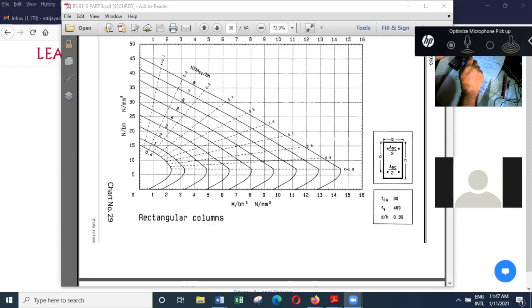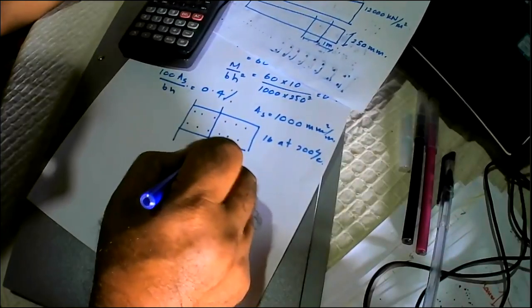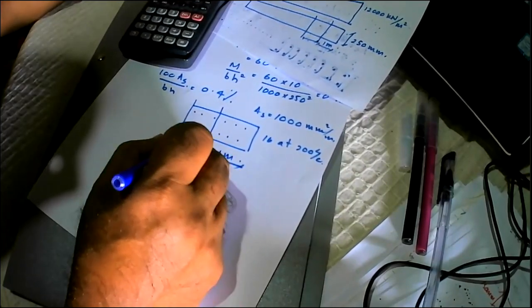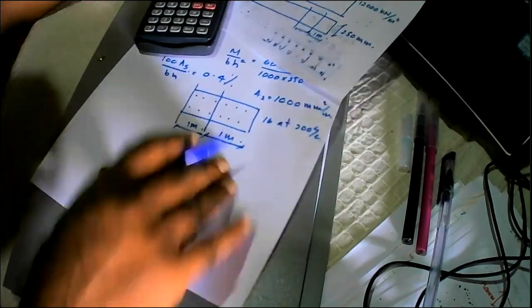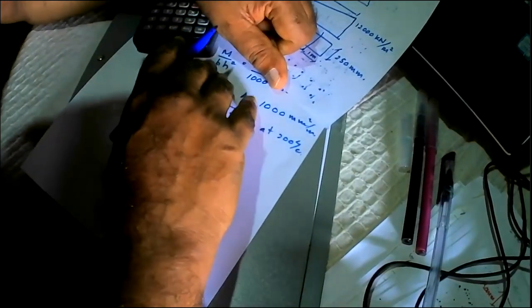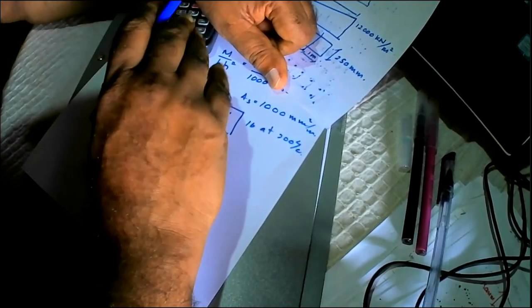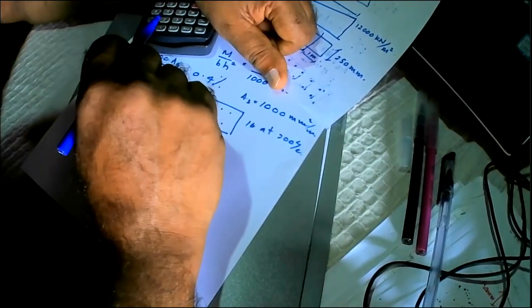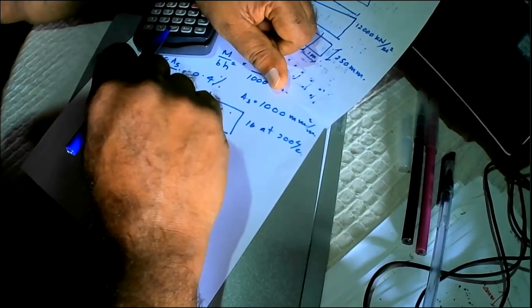But in certain situations, if the variation is high, then by using this method, every 1 meter you can have a different reinforcement. So that's the other way of finding the reinforcement. One is if you know the overall moment and the axial load, you can consider that the wall behaves like a column, and you are also sure that the out of plane moments are small.